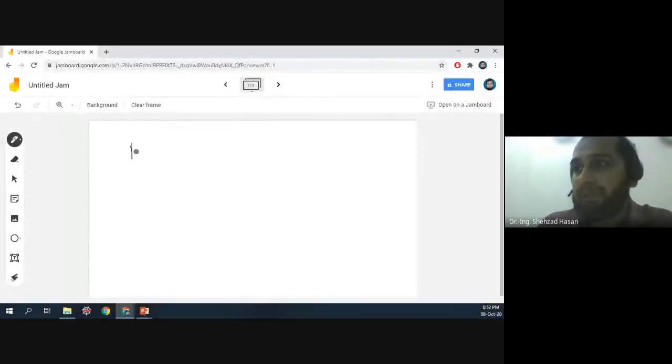One is a maximum vector length register. This is a hardwired constant, always constant for a particular architecture. For example, in our case, the maximum vector length is 64. So it's going to work on 64 elements.